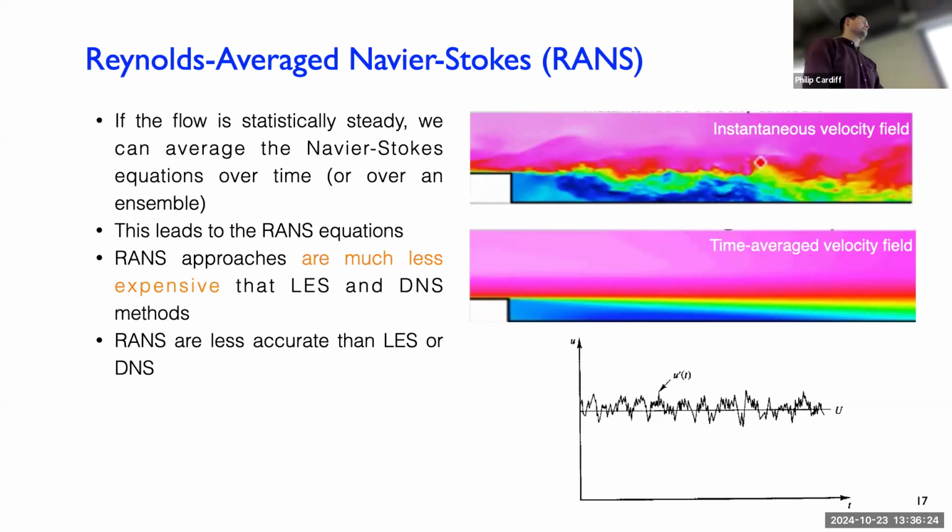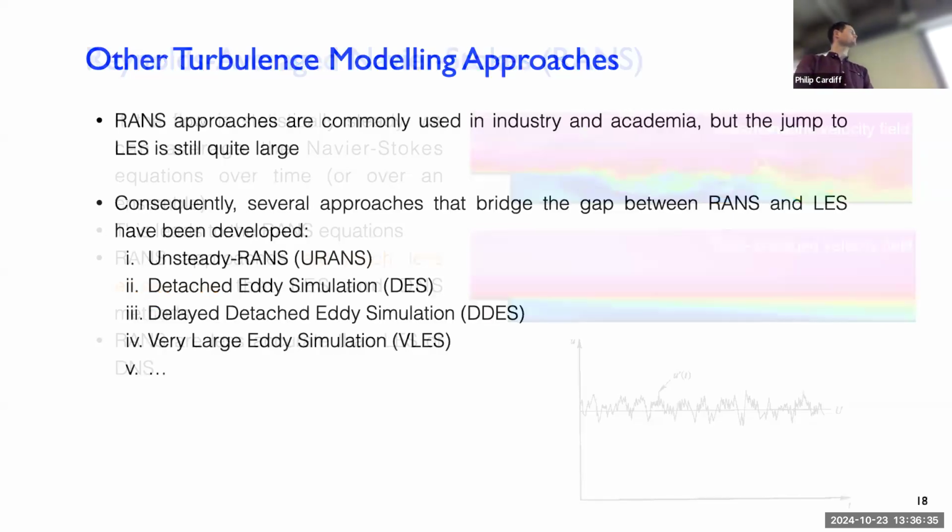So RANS is pretty cheap. You can do RANS of a full car in 3D. You can probably do it on your laptop in an hour, something like that. It doesn't need super high resolution, so it's very practical.